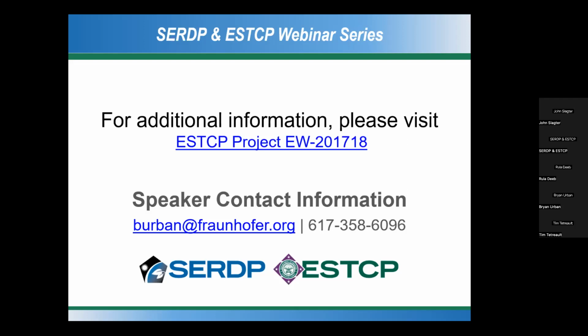So that's pretty obvious. But for the occupancy controls, you'll do the best there if you have unpredictable schedules. And so the gymnasium was a really good example of that, because they operated that facility 24/7. And sometimes people would play basketball at 3 a.m., but not every night. And so a lot of the time you can turn off those lights automatically and save a whole lot. If you have very predictable office hours and people are always around, you might not get as much savings in that kind of a situation.